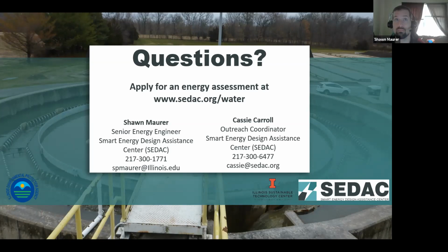Well, for most potable water plants, pumping is the biggest energy consumer on site. So anything you can do that minimizes that pumping energy, be it VFDs, pony pumps, that kind of smaller service pump that runs for low service periods, or demand management in your community or on site. Those are three really good options for limiting that pump energy consumption, and a good place to start since that's probably going to be your largest energy consumer in most instances.